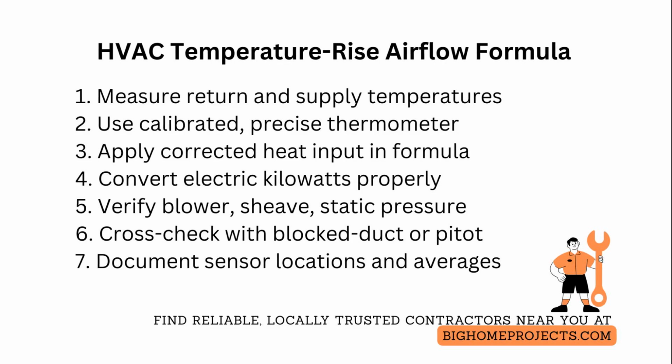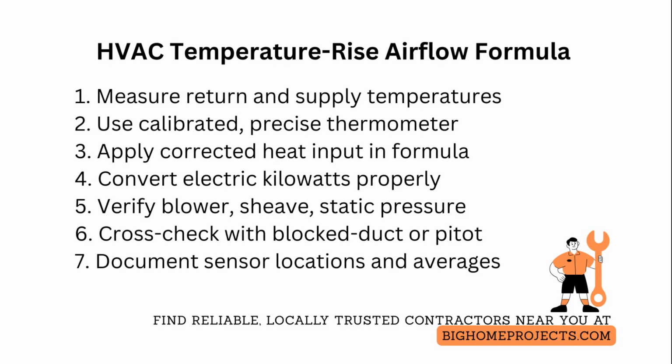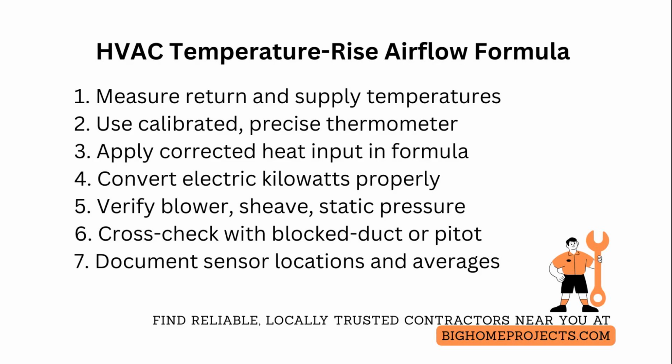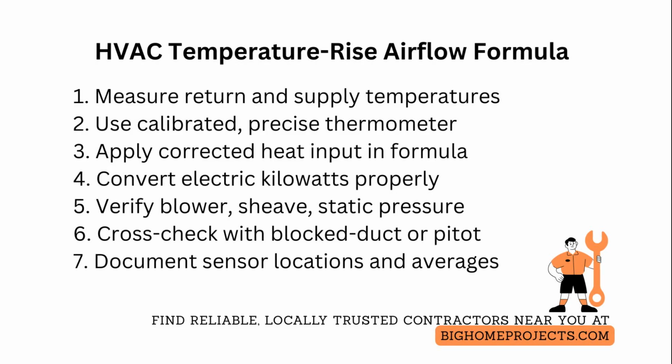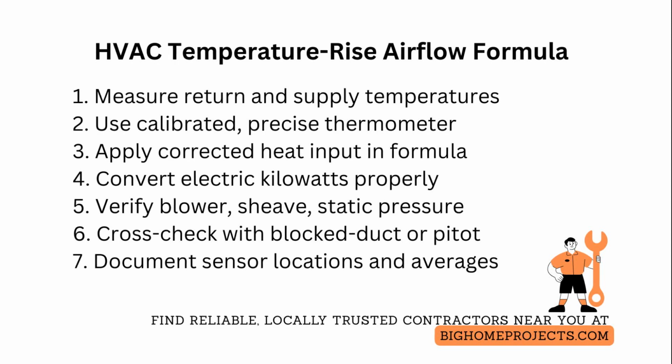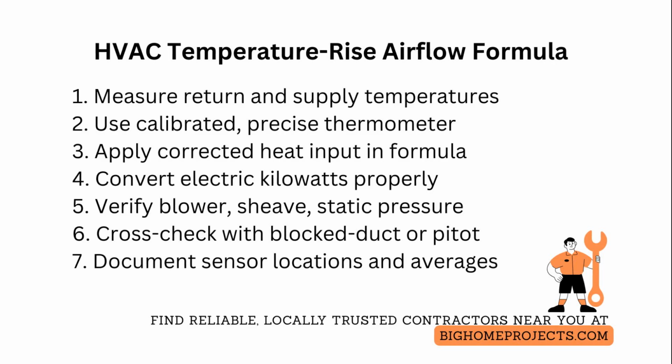When you suspect duct leakage, supplement the temperature rise CFM with a blocked duct test or a pitot traverse in the main trunk to cross-check results and identify imbalanced locations. Document all test lead connections, exact sensor locations, and the duration over which averages were taken so anyone can replicate the test. This reduces liability and improves commissioning handoff quality.